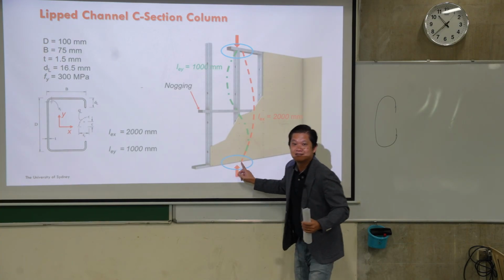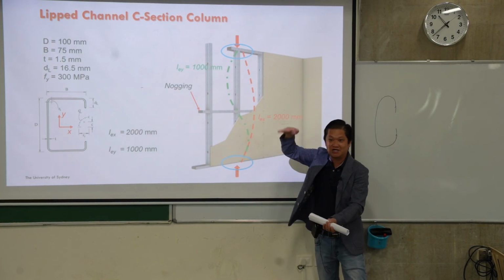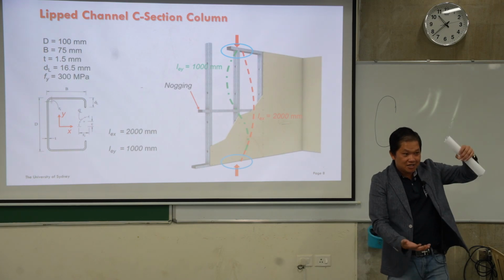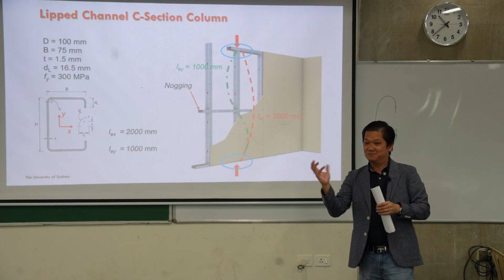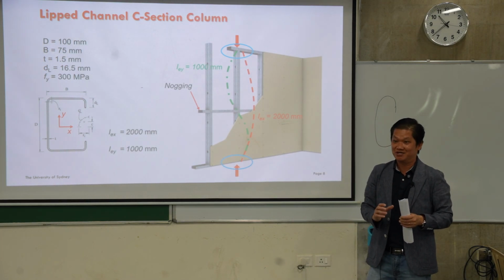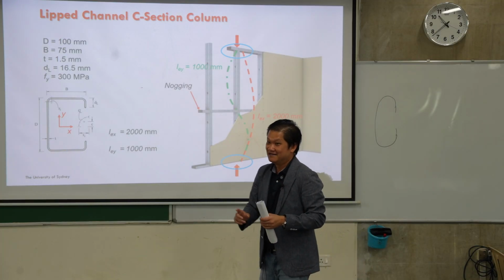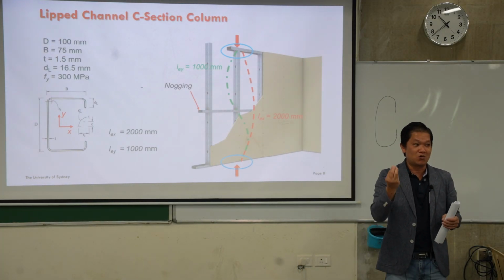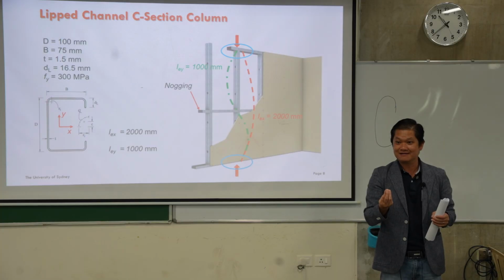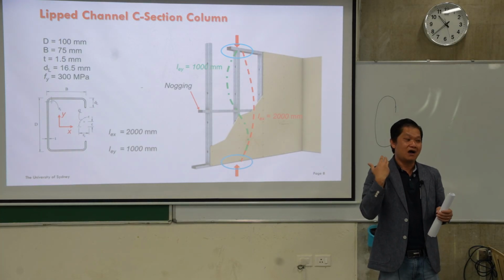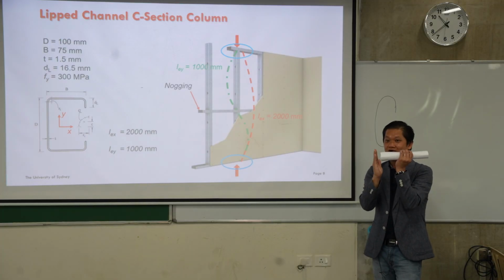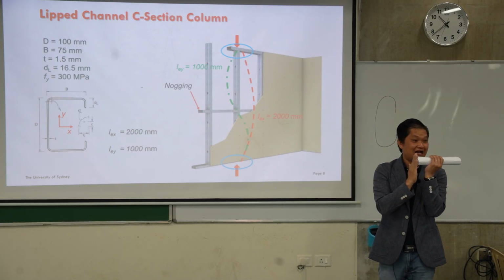Similarly here, when you weld or touch the end of the section, it helps our column increase twisting capacity. And that twisting is related to the torsional capacity, and that will affect your torsional buckling load depending on the condition of that end.